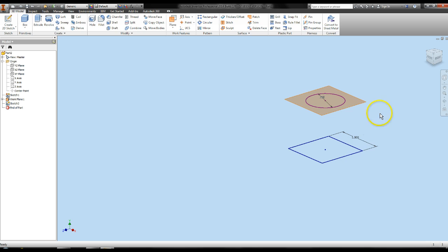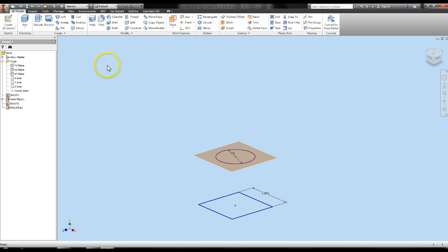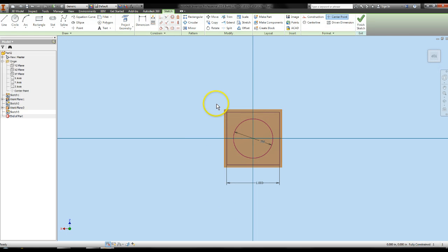And now I just want to make the square top. So I'm going to basically repeat the same steps. I'm going to say offset from plane. I'm going to select the edge of that plane, type in 1, press enter, create a sketch, and create that right on there. Again, we want to project the geometry of the center point, press escape, go over to polygon, make sure it says 4, drag that out, press done, make sure this edge is horizontal.